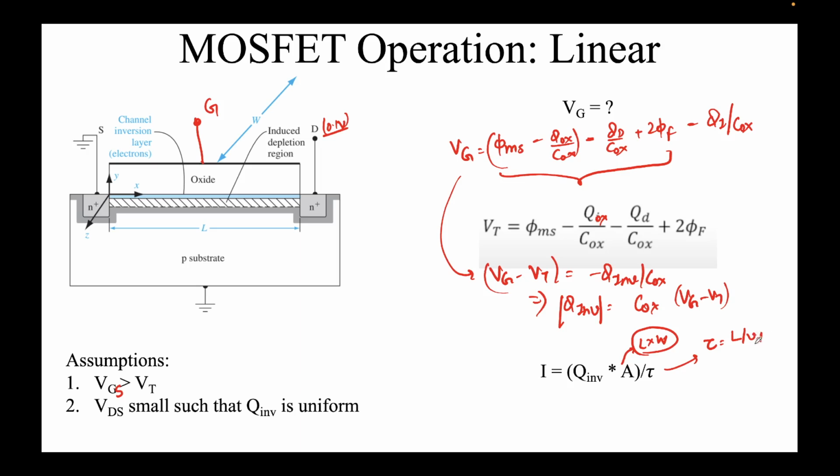What speed? Drift velocity. Now which drift velocity? In the x direction, because that's what we are interested in, right? And we know drift velocity in the low field regime is Vd equal to mu E. In the revision today we also saw that Vd equal to mu E. Please remember, Vd I'm talking about in the x direction, between source and drain, right?